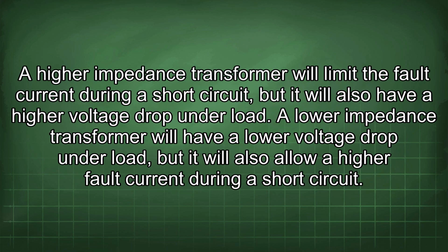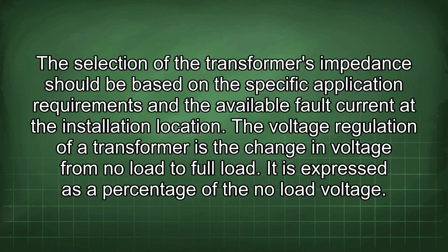A higher impedance transformer will limit the fault current during a short circuit, but it will also have a higher voltage drop under load. A lower impedance transformer will have a lower voltage drop under load, but it will also allow a higher fault current during a short circuit. The selection of the transformer's impedance should be based on the specific application requirements and the available fault current at the installation location.